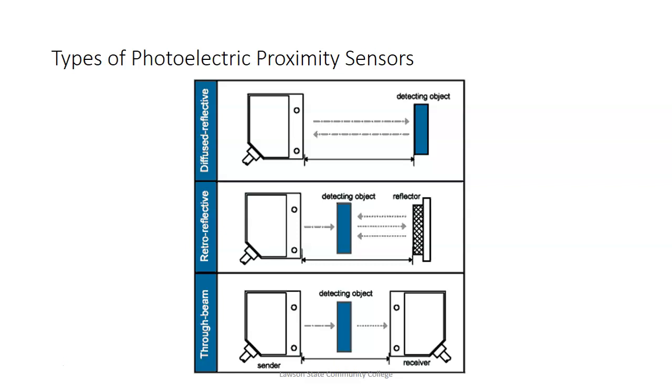So we could use it to sense shades of gray. They're not actually sensing color; they're sensing shades of gray. So on the Festo line, some of the diffuse sensors we have adjusted so they do sense black, but the sensor is very close to what it senses. And then sometimes we have them adjusted so they don't sense black. I'll show y'all that, and it puts the cylinders together differently. If it's black, then it's the other two colors, and we'll look at those. But that's what diffuse sensors depend on: reflective light.